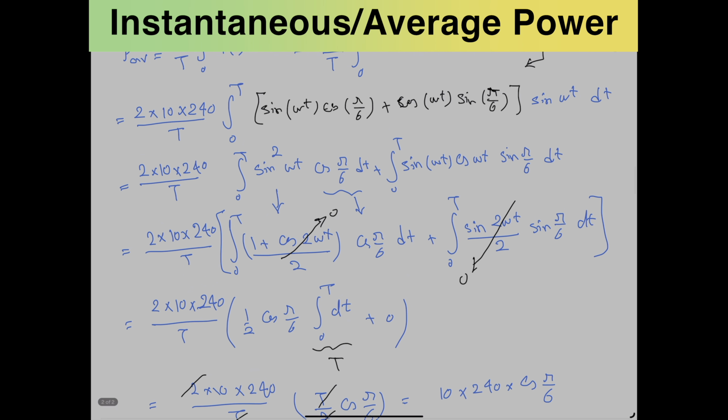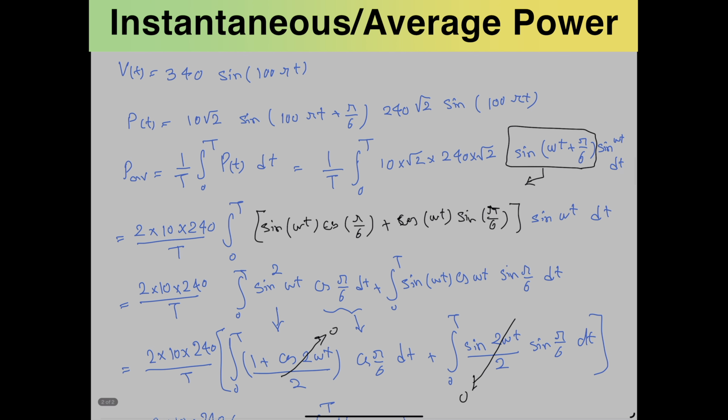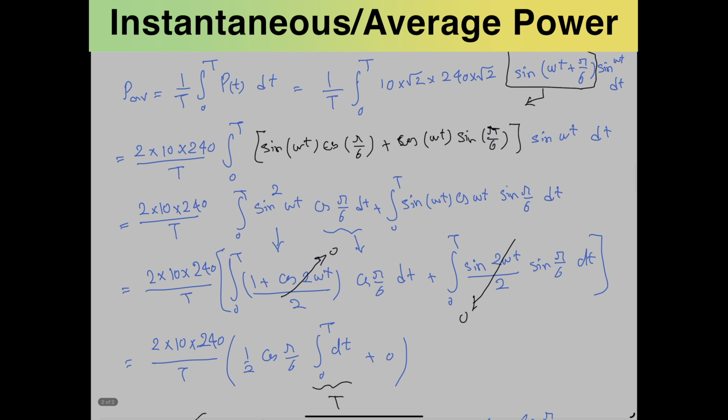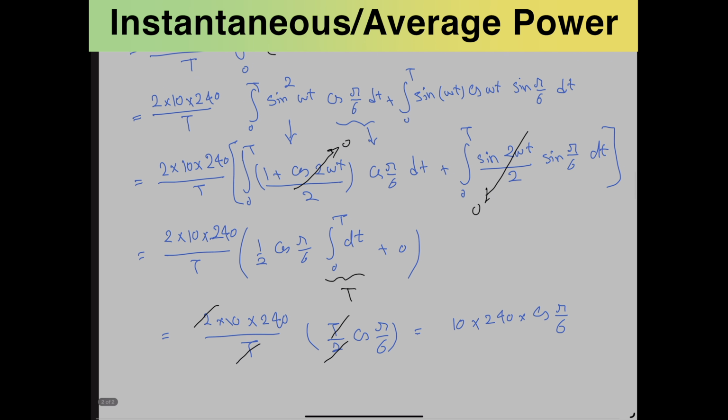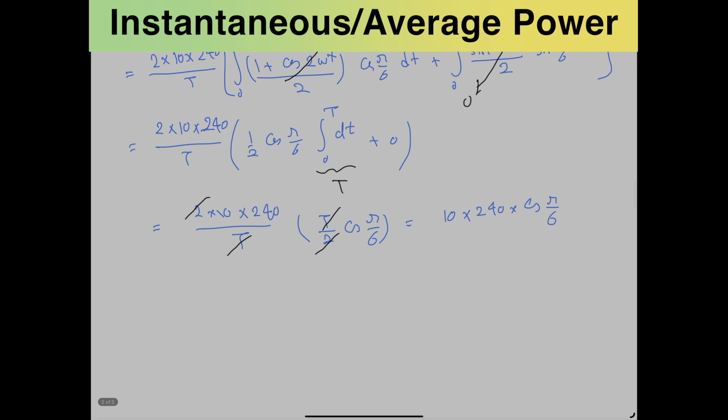And you can see how much work is required in terms of multiplication of sines and integration over them. And we need to know all the relationships between the sine squared and cos squared. However, there is a much easier way to get that average power as well, and that's what we are going to discuss next. So eventually, we know that P average is essentially VRMS times IRMS with conjugate value.